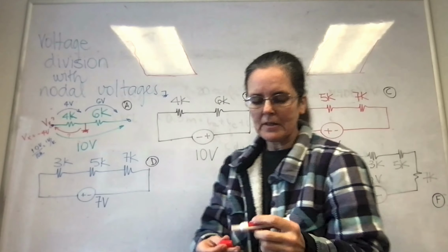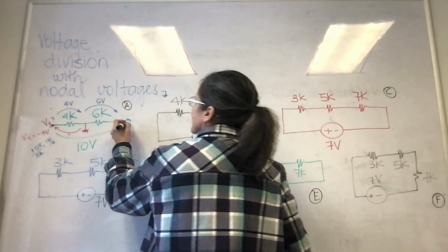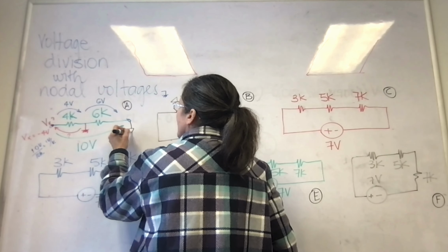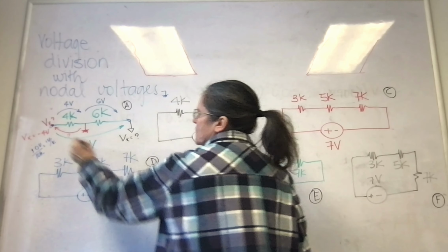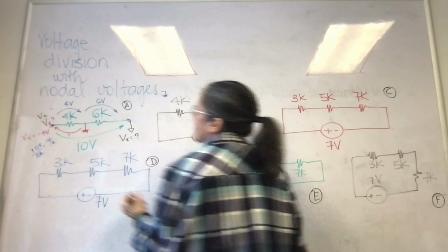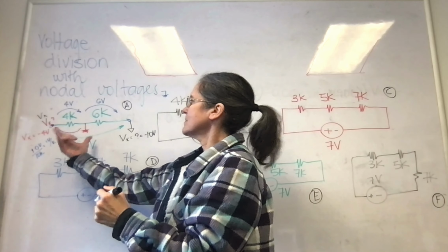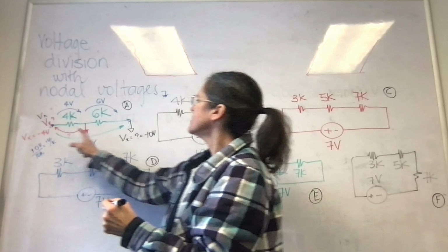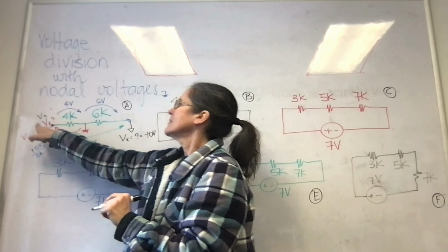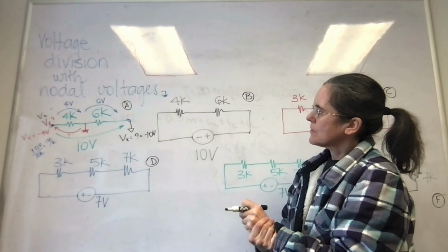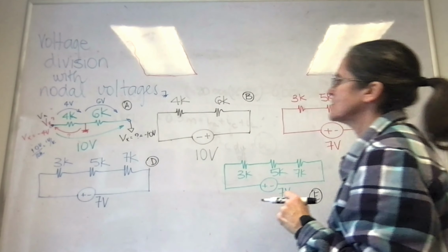If I had asked in black here, I put another ground, black, and now what is Vx? So the same Vx here, this would be minus 10 volts. Because again, I'm switching. So the 10 volts assumes that the ground is here, and I'm measuring on the arrow here. If I switch, then if the ground is on the right side, on this side, then minus 10 is on that side.